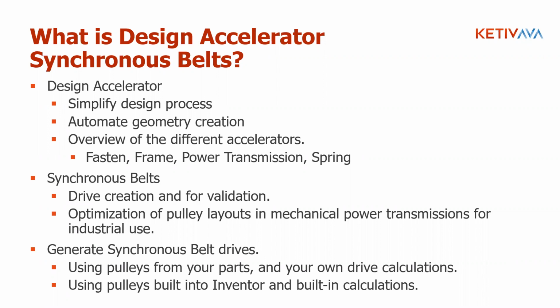They have fasteners, frame generator, power transmission, springs. The synchronous belts, you can do drive creation for validation and optimize the layout of the pulleys for the RPMs and outputs and power transmission that you need. There's a few different ways to do it. You can generate the belt drives using pulleys that are from your parts that you've drawn in Inventor, or you can use pulleys that are built into Inventor with their calculations.